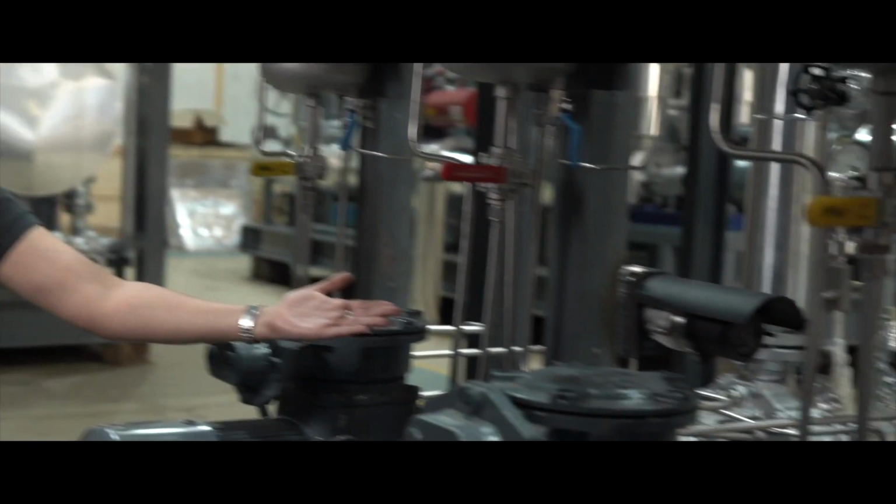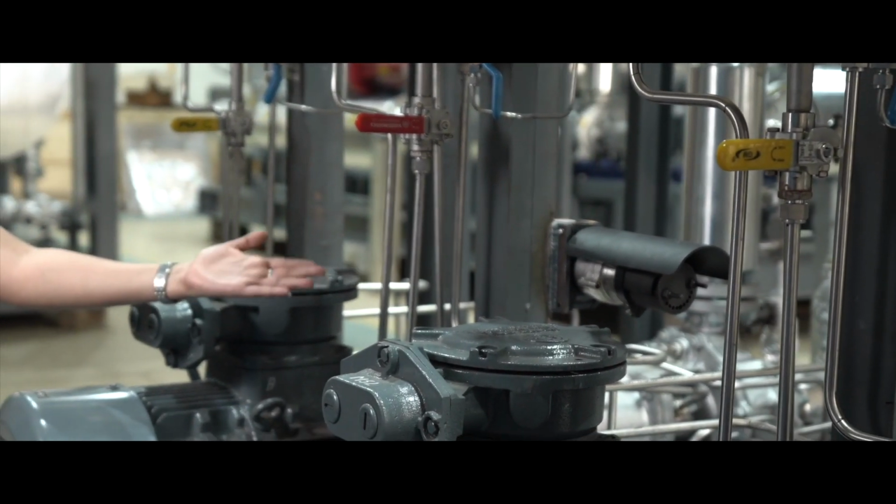Heating kerosene to a high temperature makes it very hard to pump. So it's very hard to design the proper pumps for this process. So the client wants a very dependable process. So GPE and KLM took about 3 or 4 days and optimized the design of the pumps so they would be safe and economical and work as required. To ensure that the entire system is tripped in case of a potential fire hazard, we have LEL detectors which are installed at areas which have possible leakage.